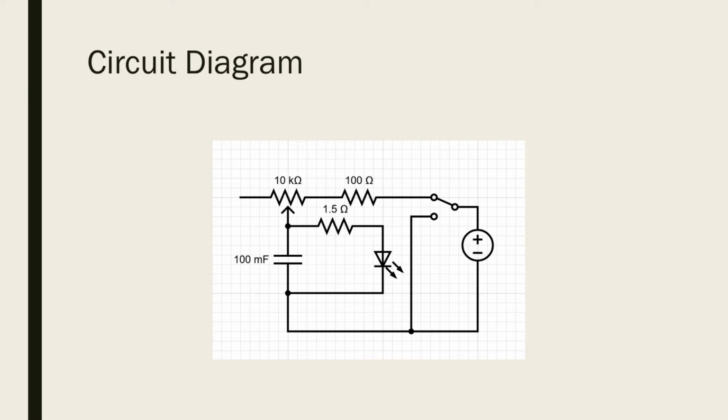Once it is past this segment, it continues down to the node on the bottom side, where if the switch is as shown currently, the current will obviously not travel up that wire. But if it is switched, the current will bypass the voltage source and travel through the 100 ohm resistor and the potentiometer, effectively discharging the capacitor.